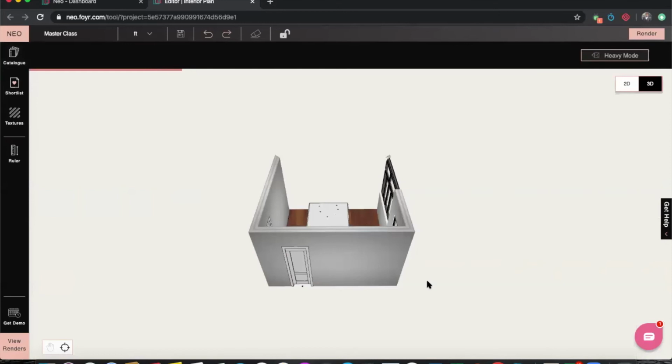As you guys can see, it was fairly simple. I think it took me hardly 4 to 5 minutes to readjust the layout of the inspiration as per my bedroom layout. And now we will just do some enhancements in 3D mode and in ceiling plan mode, just to make it perfect, ready for the render. So I will just quickly show you how you can do this.